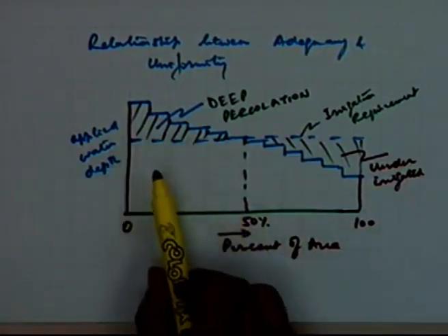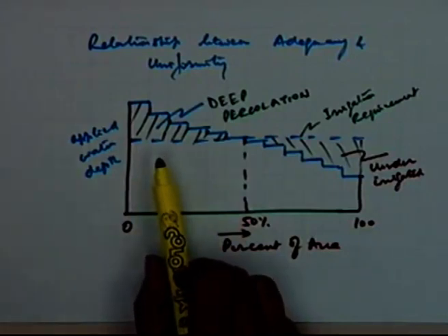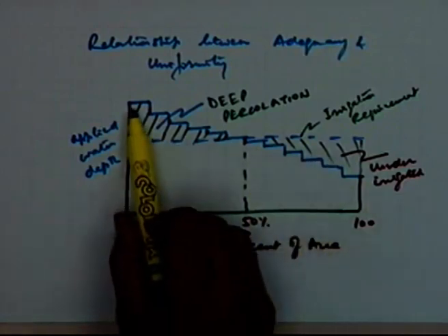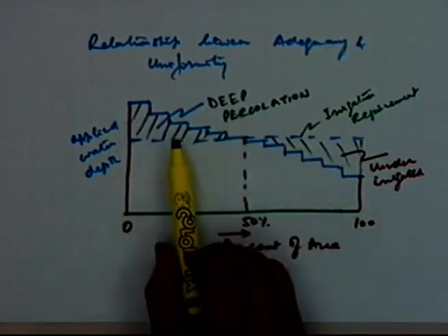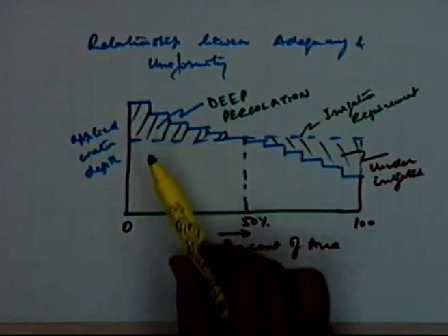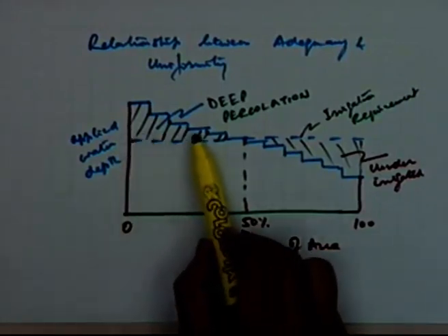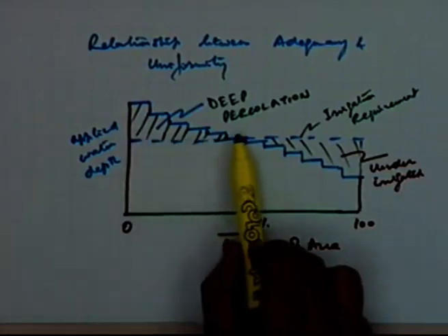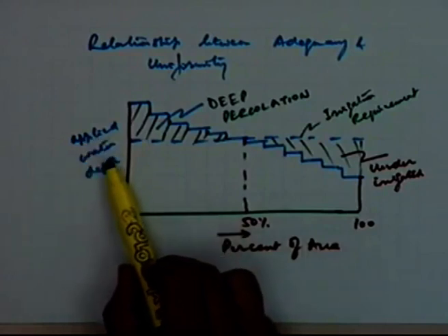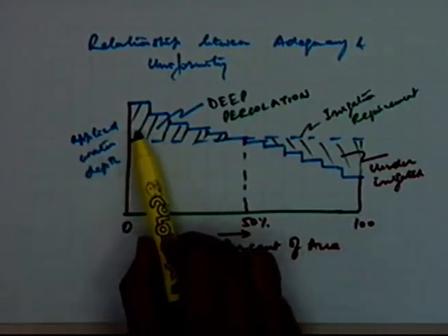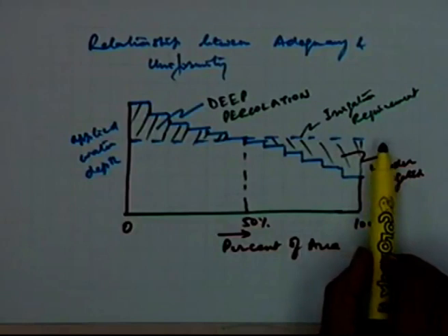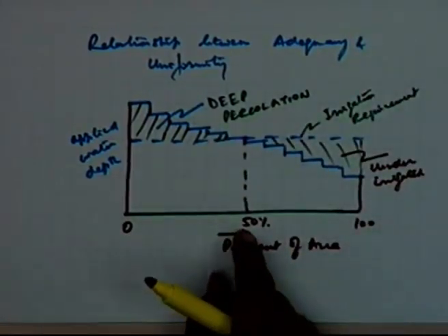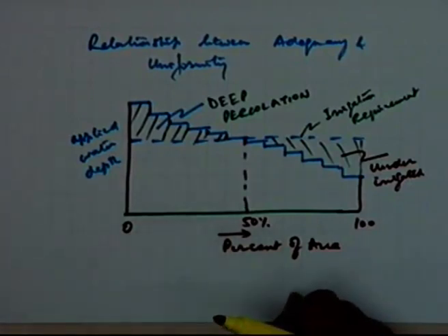If you wanted to have a higher uniformity coefficient, then for the uniformity coefficient to be higher, this disparity, this extent of the area should have been minimal. So you should have got a distribution pattern which is giving you the actual depth quite closer to the required depth. That is what you have to achieve for a specific level of adequate irrigation, or the adequacy of irrigation.